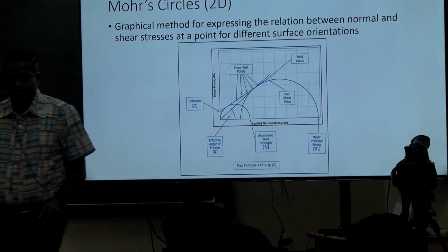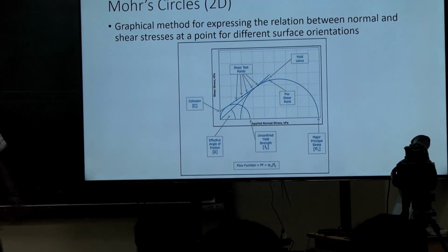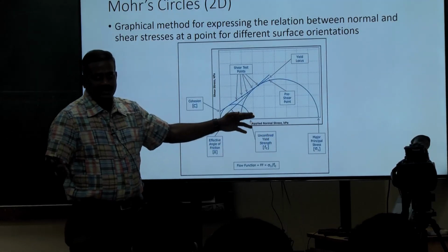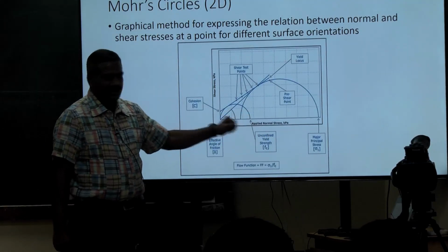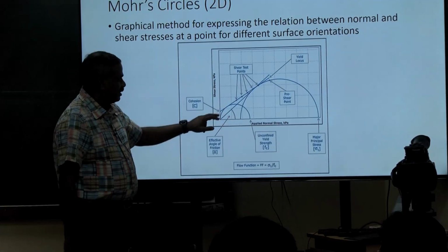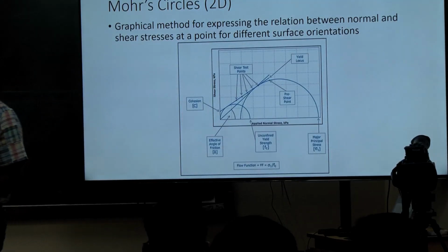Okay. Any of you remember the Mohr-Coulomb law? So, C is the cohesion, right. So, tau is equal to C plus sigma, where sigma is the normal stress, right. So, that is the cohesion. Again, I will show the equation for others in a minute. So, that is the intercept here. That is the cohesion of the powders.